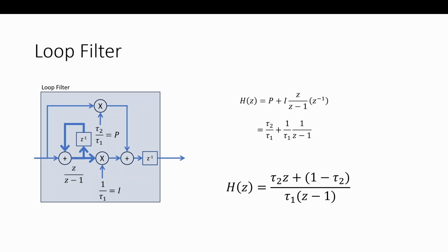In terms of that, I have the transfer function in different forms. I could have it shown as the proportional and the integral relation, or as one combined transfer function. We like the combined transfer function because ultimately I want to get the open loop gain and I want to make that as simple as possible. And if I can describe that as polynomials of z, we'll be able to use these tools directly.